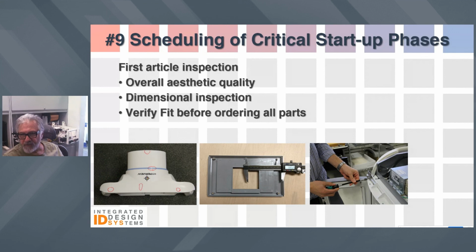So if you don't order all the PC boards at the same time and you have the benefit of evaluating its fit to the part early on in this production startup phase, you can always modify the PC board and then order them to comply with the part. Some companies frown on doing something like this, but it's a reasonable and sensible alternative to delaying the project or going through some costly tooling revisions. So that's what I mean by critical startup phases.